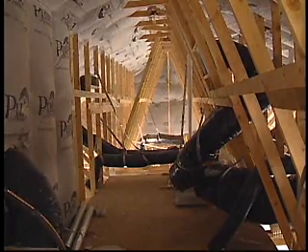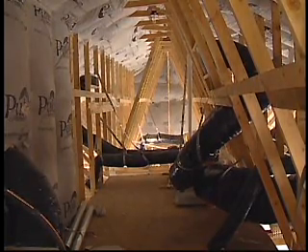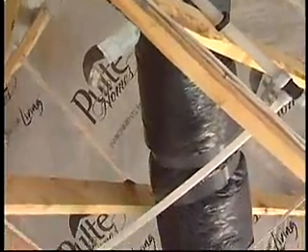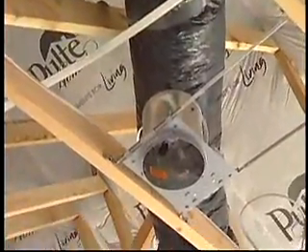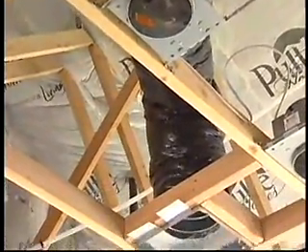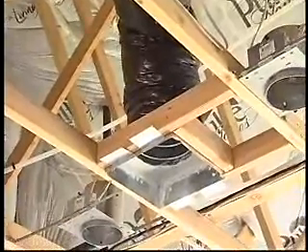Yeah, you really have to make sure that you have a non-restricted duct system. And in the case of a production builder, what you want to do is see how much air needs to flow to each room, and the worst case for that room. And then you design your whole duct system to deliver that much air to each of those rooms.